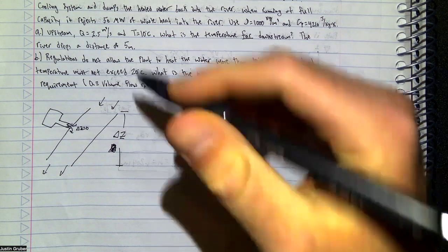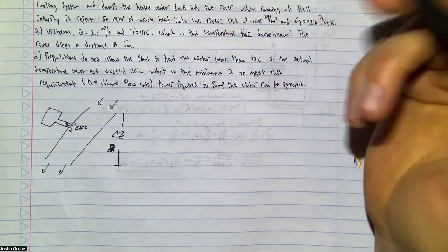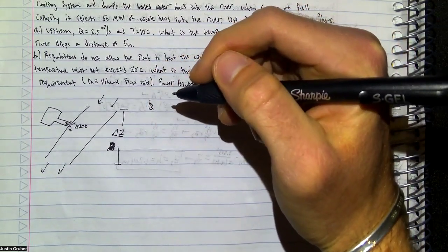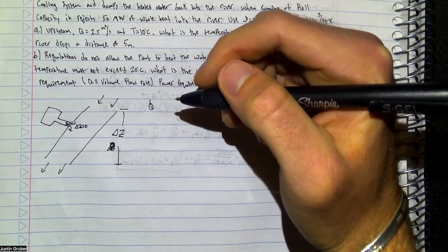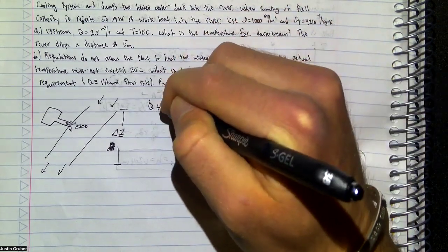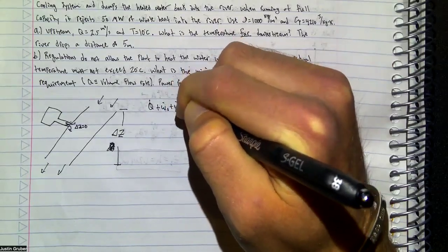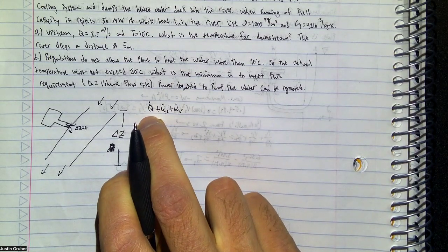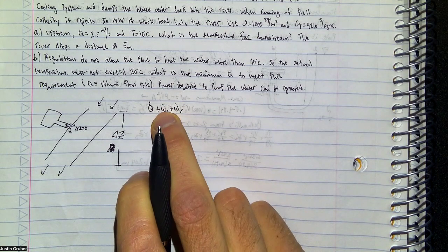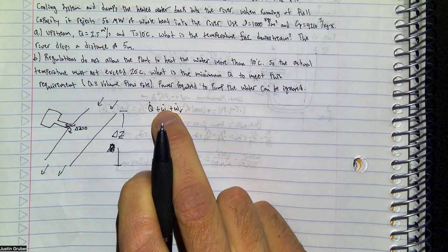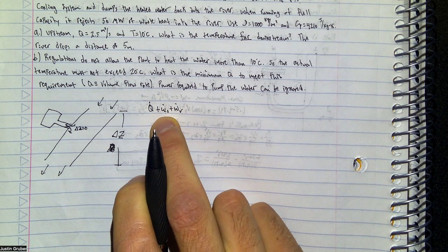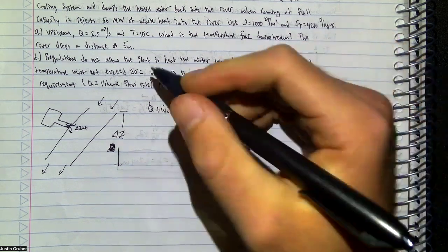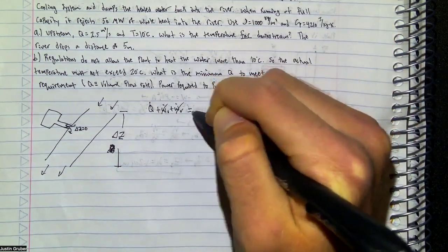So first off, let's write our actual energy equation, at least in the form where we're already taking off the d by dt term. There's no time derivative going on here, so I'm not even going to write it. We've got Q dot, that's our heat flow, our megawatts. W dot S, that's our shaft work. So if there was some turbine in here, some turbomachinery, that would be that term. And then W dot V, that's viscous work, friction stuff. But for the scope of this problem, those are both 0, so we can get rid of those right away.